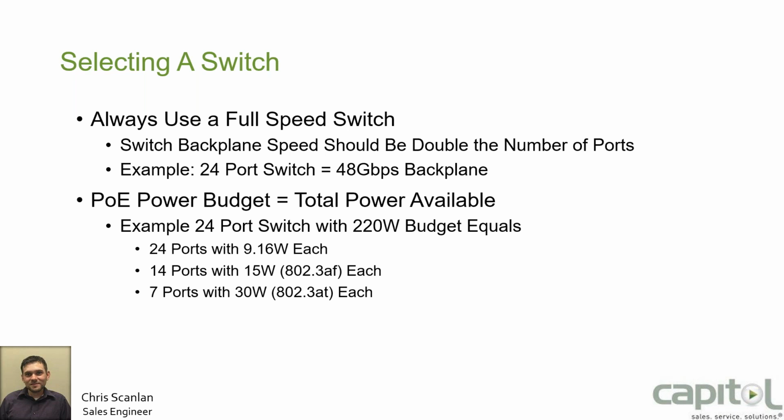PoE power budget. This is something also to really keep in mind. If you're putting devices on a PoE switch, you want to make sure there's enough power built into that switch to power your devices. And Luxul does a great job of putting a lot of power in their PoE switches, so you don't have to worry about this as much. Some manufacturers, you may see it's a 24-port PoE switch, or even PoE Plus switch, but it's 100 watts.